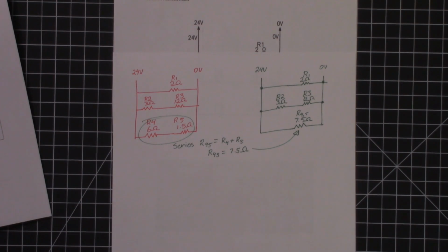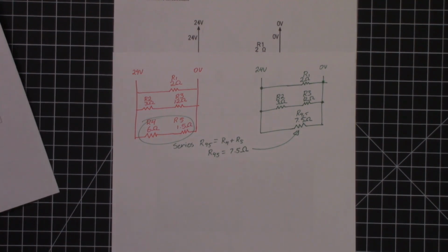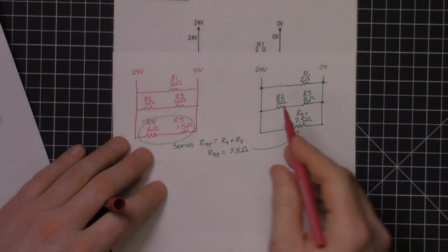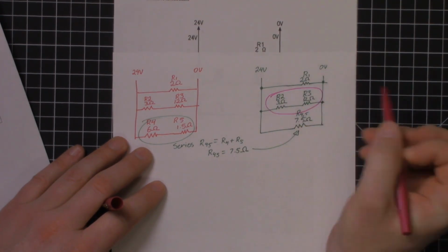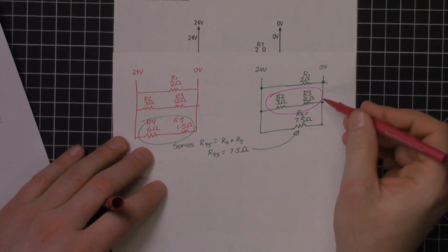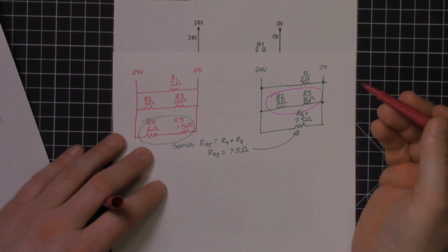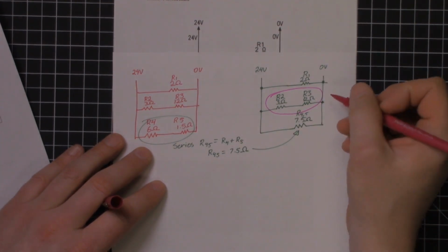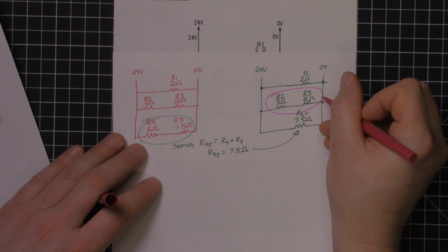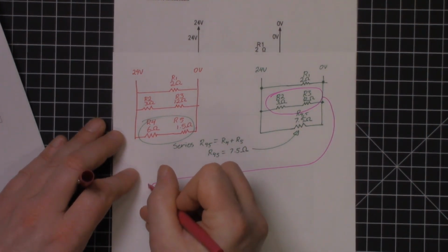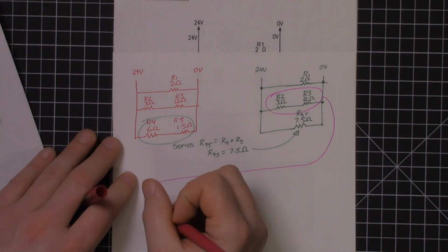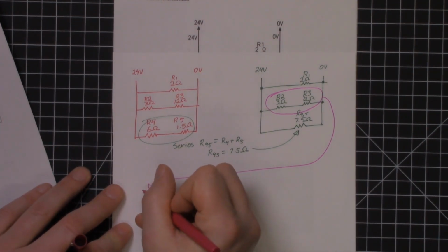Now, the next thing we can look at is, are there any other resistors that are in simple series or simple parallel? And we probably could have done this in one step, but at the beginning I'm just pointing out this way. Like these two guys, resistors 2 and 3, they are also in series, so we can treat them as such. So I'm going to make a little line that's going to bring me back here. Okay, and I'm going to say that resistors, those are series.